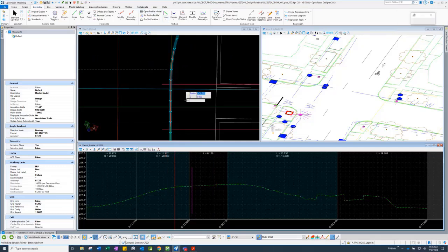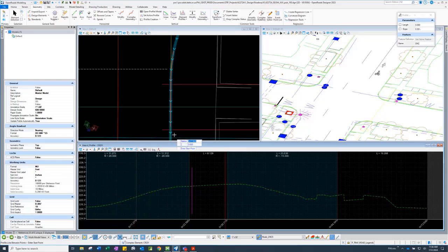Okay. So we're going to draw another line. I'm going to just go through the motions real quick here. 225. So you're just using the intersection snap to get the station. To get the station. And this makes my notes on my table a whole lot cleaner because I don't have to write stations down anymore. And the Z values aren't critical. They aren't, because you can use these as construction lines to draw from in the future once you lay your lines out. They are construction lines, just like in Plan View. In profiles you can use construction lines.